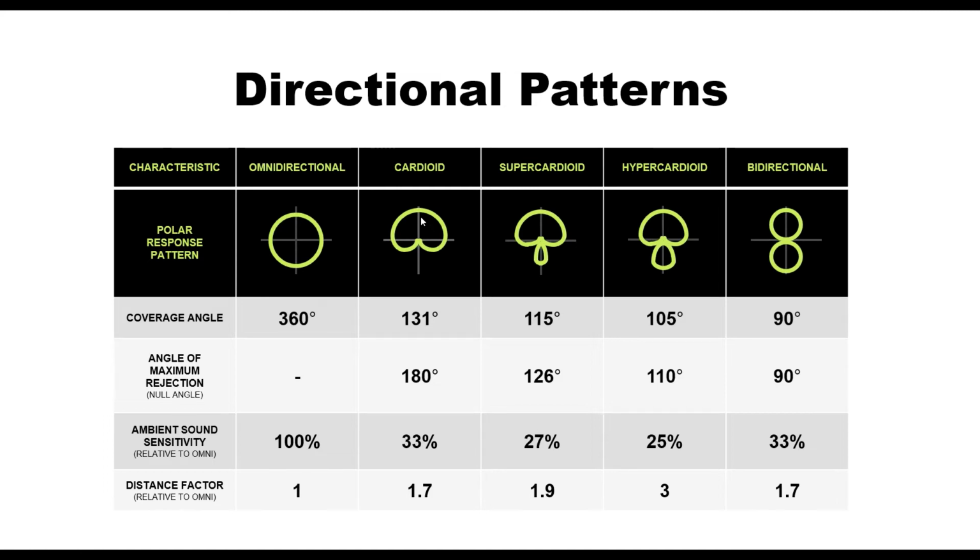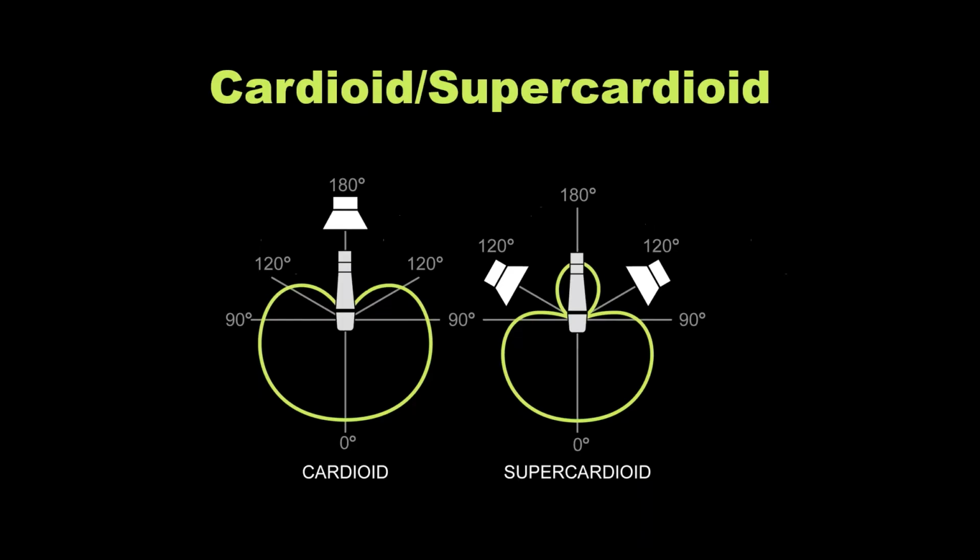You can't always use a headset mic. That's where you start thinking about going to cardioid or supercardioid pattern microphones to sort of maximize that gain before feedback situation. But again, the loudspeaker placement becomes really, really critical here, particularly if you're using on-stage monitors or floor loudspeakers. And now, when we talk about cardioid versus supercardioid, you need to be aware of where that null is.